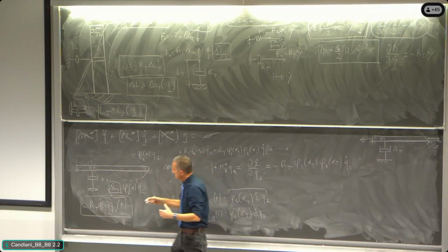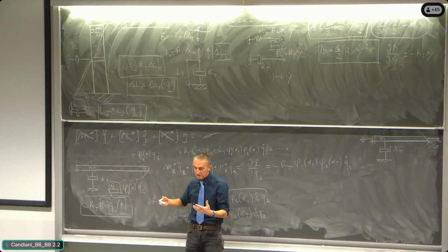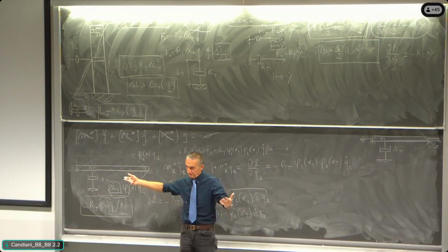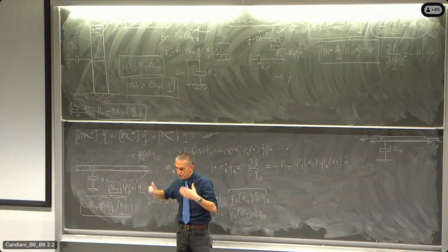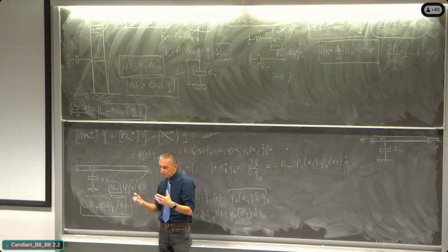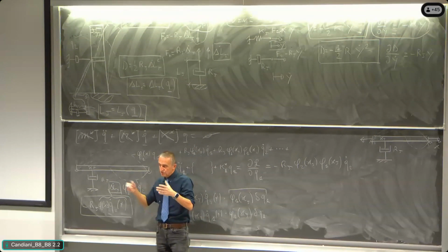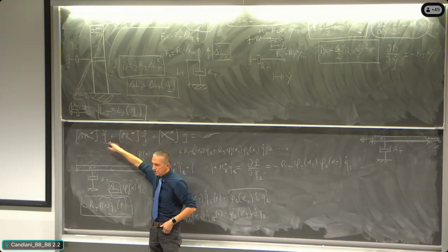So when I am giving the free motion, the system is moving according to all the principal coordinates that can vibrate. So the general free motion of the system is associated to the superposition of all the natural modes. Each of them is vibrating, moved by its own coordinate.